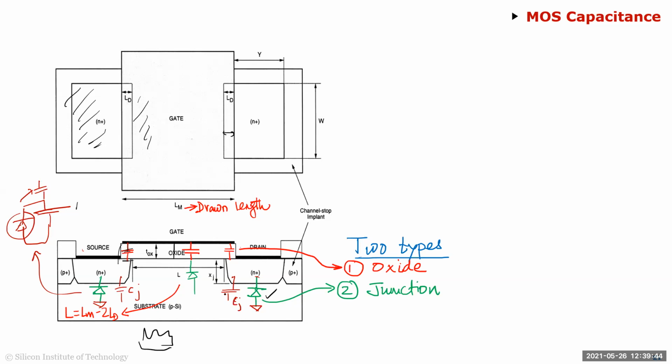The gate cap, you can kind of think of as a parasitic cap because all you're trying to do is control the channel, but because of that you also get an oxide capacitance, and the source and drain are also parasitic caps. And you see that because of these overlap regions, there is a tiny amount of oxide cap between the gate and straight to the source and drain. So you have these tiny caps, they're called C overlap caps. So you have those caps.